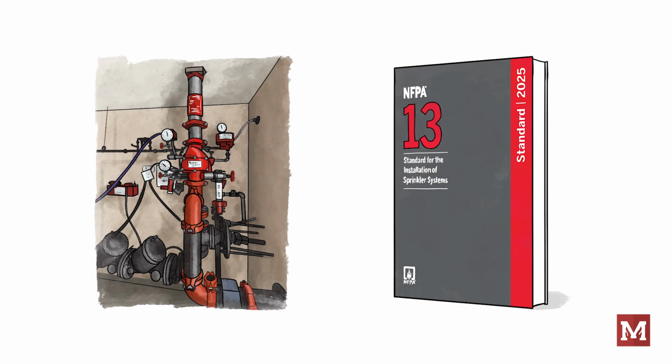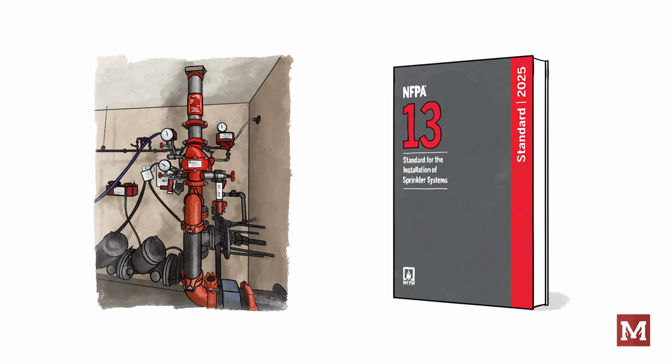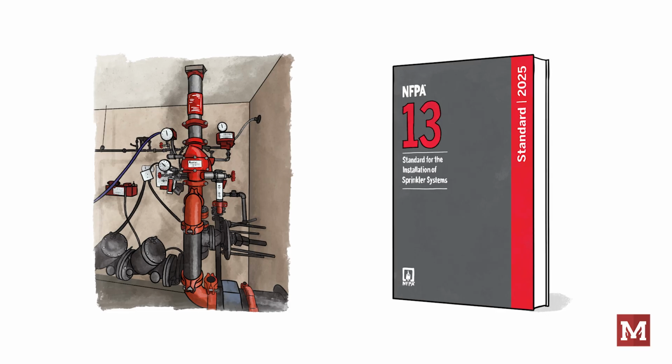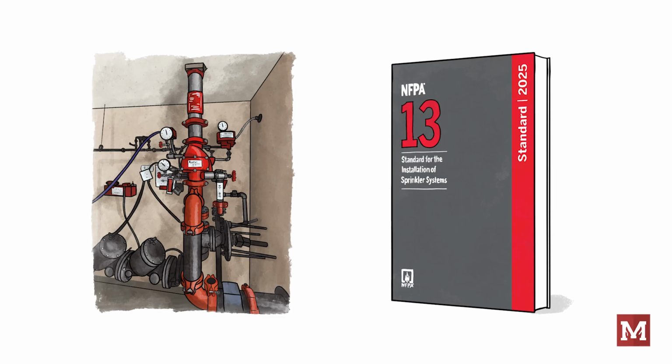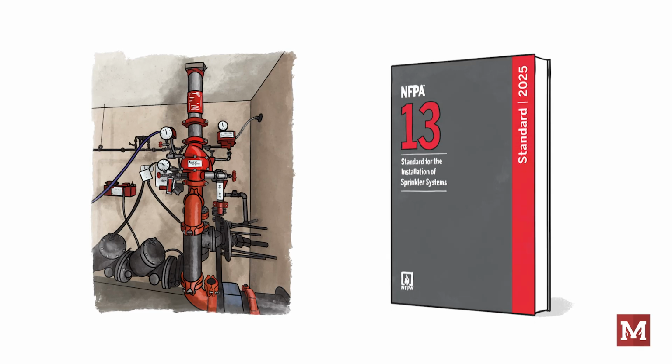It doesn't do the building owner or occupant any favors if we design our system for light hazard, which requires a density of 0.10 gallons per minute over an area of 1,500 square feet and requires a hose allowance of 100 GPM, when the occupancy hazard class is really ordinary hazard group 2, which requires a density of 0.20 over 1,500 square feet with a hose allowance of 250 GPM. That would be a pretty big problem and cost a lot of money hydraulically reinforcing the system later on.